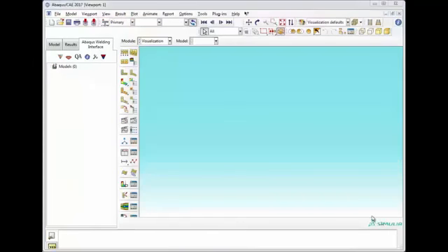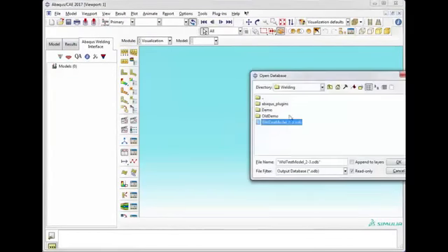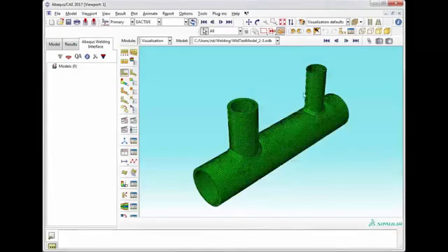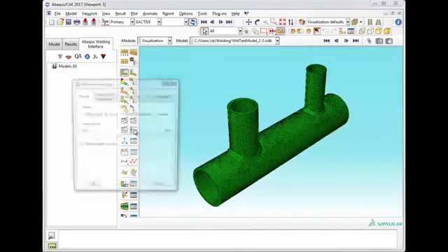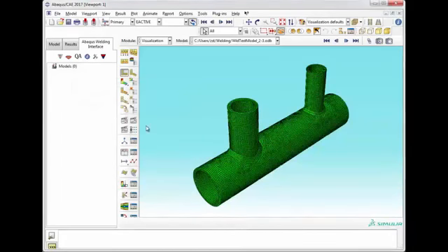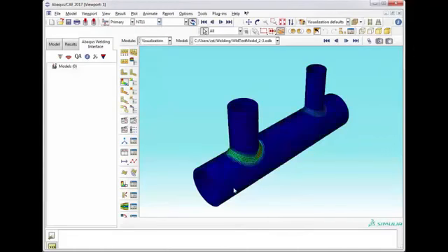All right, now if we want to look at results, contouring results from the AWI, what we'll do is go ahead and open up an existing ODB. This is results from one of the QA problems, essentially the same model. The first thing I'm going to do is change this animation. We'll put it about halfway in. We're going to slow down the animation a little bit, and then we're going to contour temperatures.